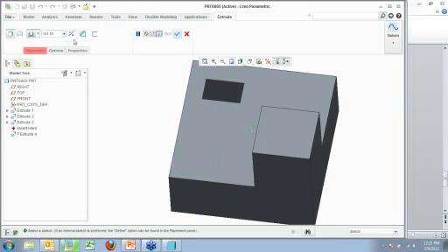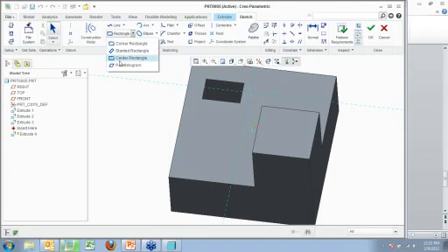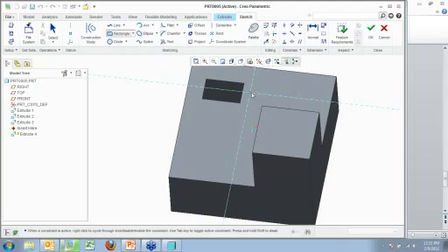And as you noticed before, I showed you this new center rectangle, which allows you, when you're creating something, a lot of times your start part might be a square about the center. Now I can do that in 3 mouse clicks. Select the tool, select my center point, and now snap it. Now that's a square. Before, like you saw in Wildfire 5, that was I want to say 7 or 9 mouse clicks, just there by itself.